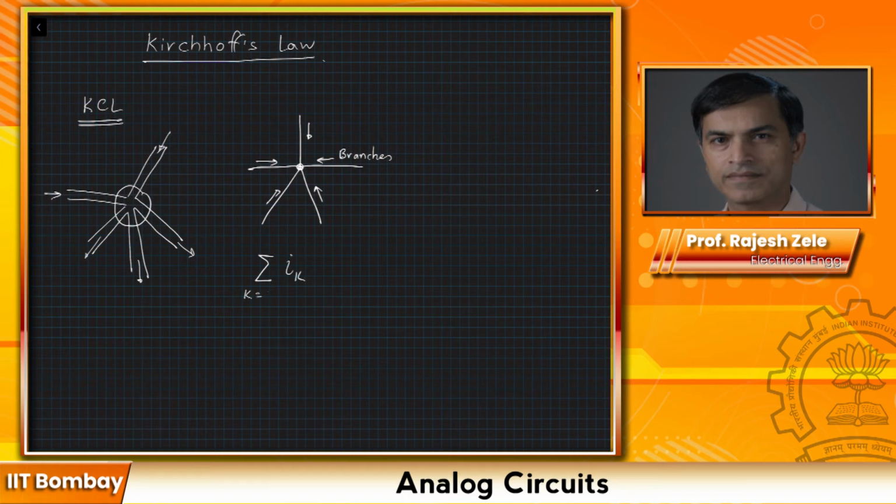Important thing to remember here is the direction of the current. If you don't look at the direction correctly, then you may get a wrong answer. So in this particular law, we are assuming that all the currents have the same direction. Okay, so this is Kirchhoff's current law. We will be using this quite a lot. The next law we use quite a lot is Kirchhoff's voltage law,